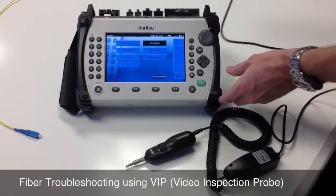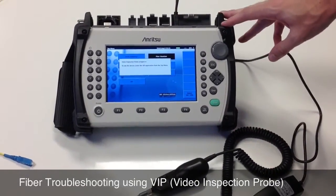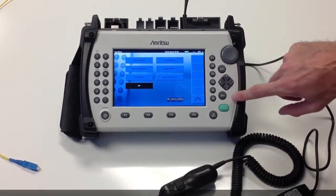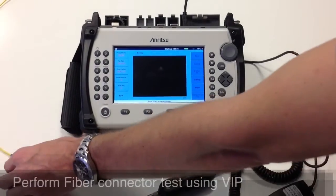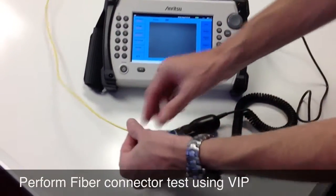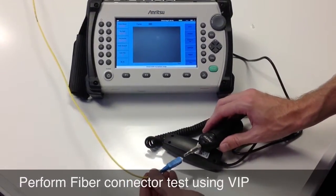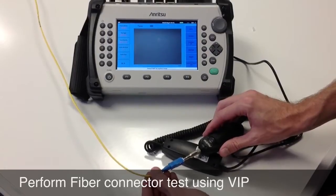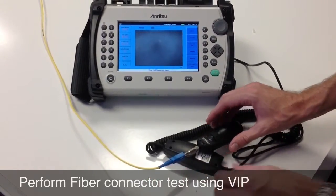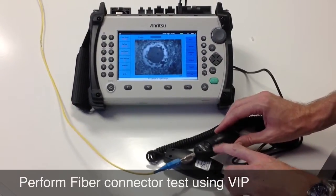Since the majority of fiber problems arise from dirty or damaged connectors, we are now going to walk through our video inspection probe test. Connect the VIP into the USB port and enter into the VIP application. Insert the connector into the video inspection probe, and then use the focus knob to get a focused connector on the screen.